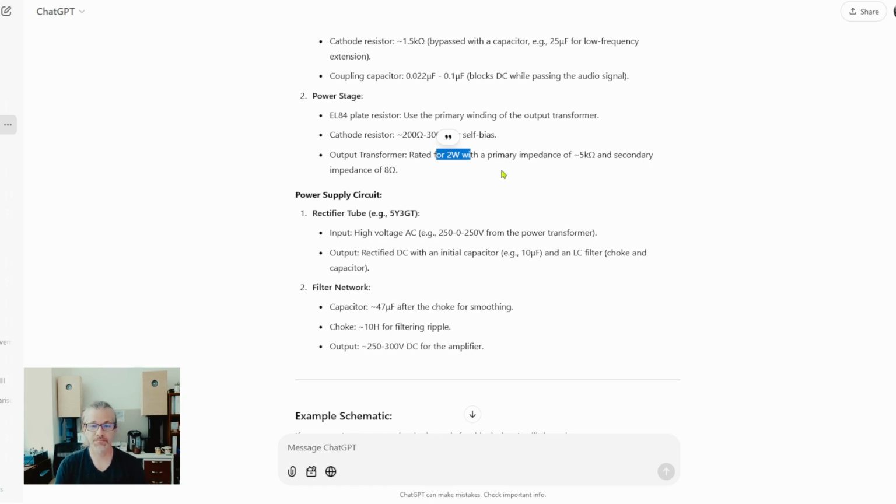Probably I would recommend a 5 watt rated output transformer. Maybe you can find a 2 watt. It will be super cheap, but probably not very good sound quality. Such transformers are really built for ultra budget and not for sound quality. I have not really seen any single-ended output transformer made for quality purposes which is less than 5 watt.